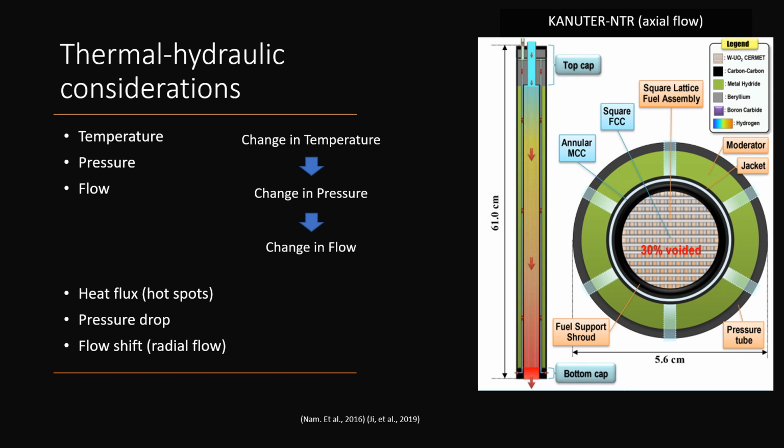And what that square lattice geometry does is control the flow of the hydrogen, enabling as much heat to be exchanged from that fuel rod to the medium flowing through that fuel rod. Also, the control of the flow helps reduce the amount of pressure drop as the hydrogen accelerates through the length of that fuel rod.